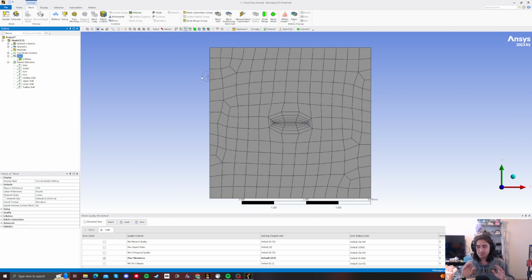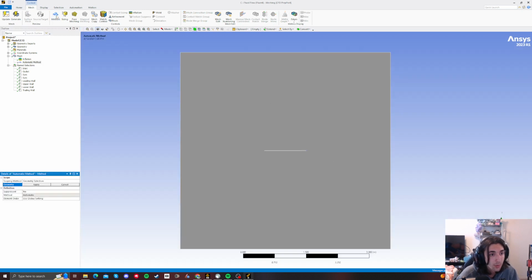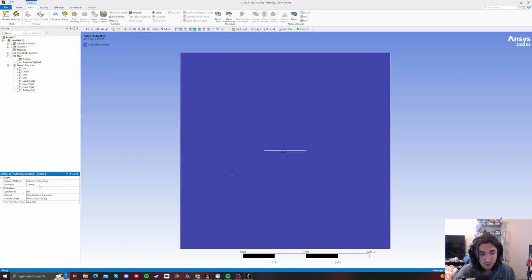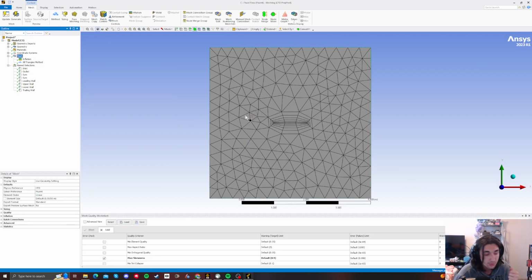Alright. So we're doing okay here, but we can get a little bit better. So we'll go to method. First select the mesh you're doing, which is always going to be that. And then this is going to allow us to change how it's doing the mesh. So instead of using quadrilaterals, that's a hard word to say, we're going to use triangles. So yeah, there you go, triangles.